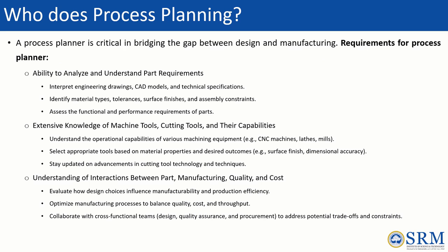So what are the skills required for a process planner? An effective process planner must possess several important skills. First, they should understand the engineering drawings, material specifications, tolerances and functional requirements. Second, they must have extensive knowledge of machine tools, cutting tools and their capabilities. Third, they should understand the interactions among product design, manufacturing process, quality requirements and production cost. Effective collaboration with design, quality and procurement teams is also very much essential in developing a process plan.